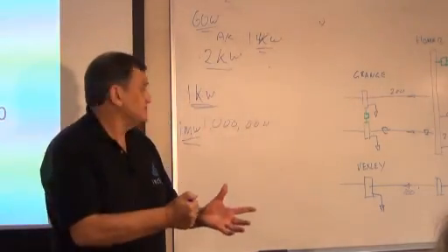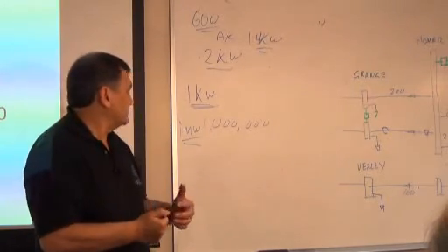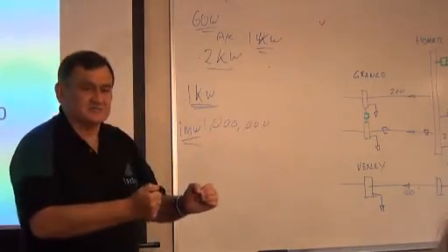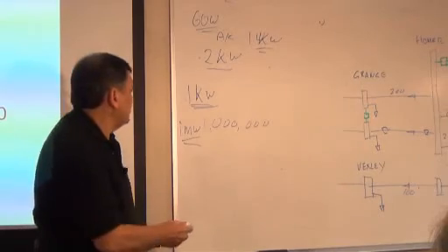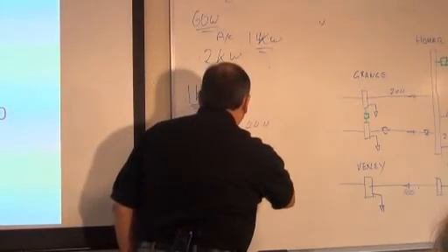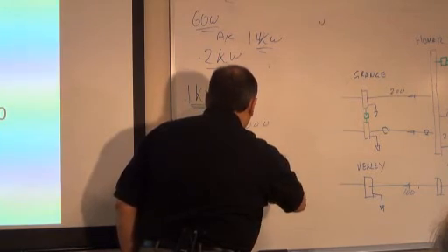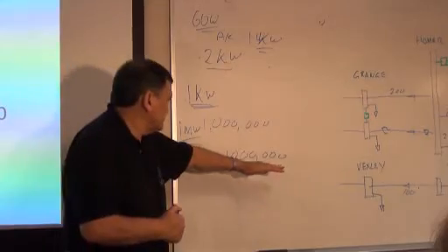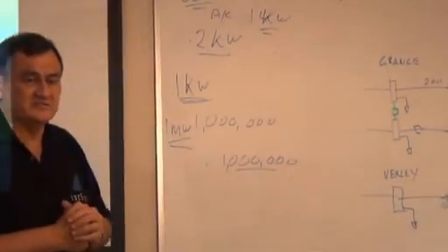It will be 1,000 times 1,000, which would be a megawatt. So a good rule of thumb is that it's a megawatt for every 1,000 people in their service territory. So if a utility has 1,000,000 people in its service territory, then 1,000 megawatts is needed to serve that, because each of those people is a kilowatt.